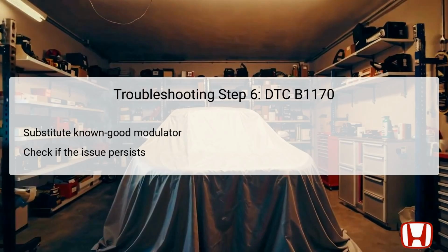It is important to ensure that the substituted components are functioning properly to avoid introducing new issues into the diagnostic process. In the 7th step, if the initial assessments do not resolve the issue, the technician will use the Gauge Control Module 36P connector for the ABS Modulator-Control unit to check for continuity with terminals number 1 and number 19 connected to terminals number 1 and number 17 of the ABS Modulator-Control unit 25P. This represents another critical contact point to verify communication pathways.